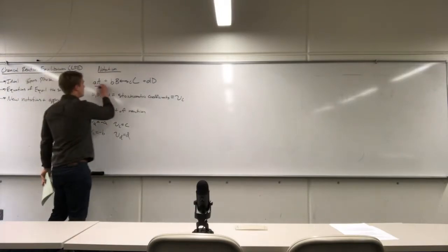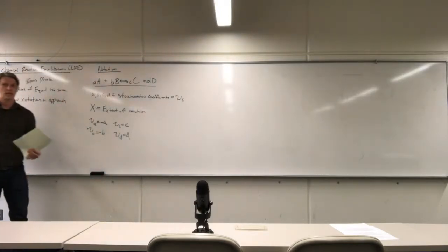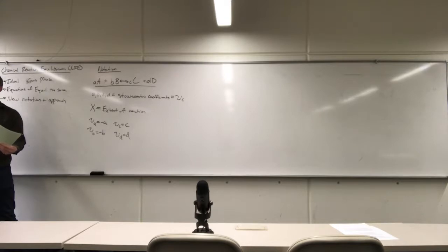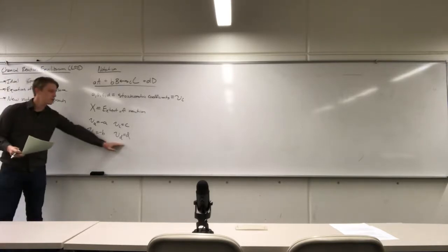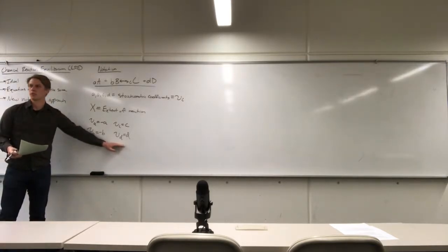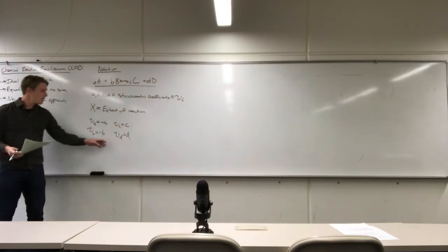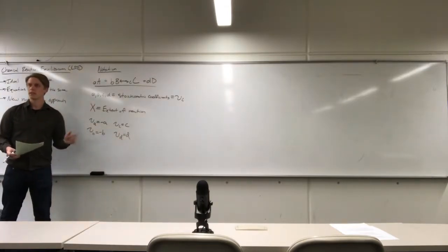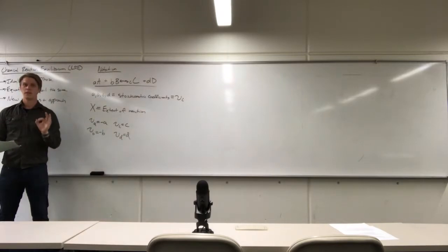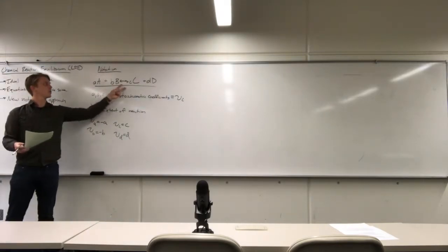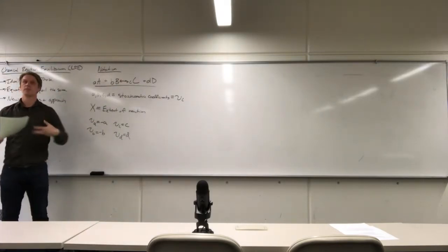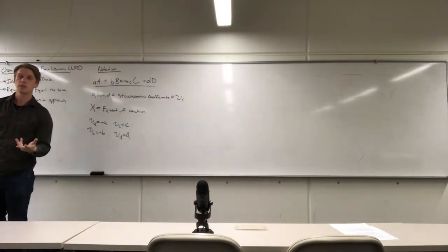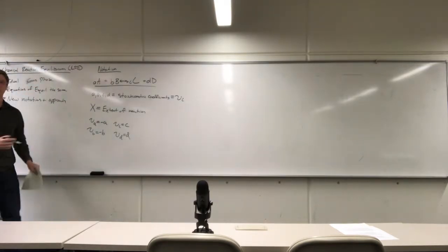When I write out a reaction, I don't actually know which direction it's going to go. That's going to be dependent on what the feed conditions, what the temperature conditions, what the pressure conditions are. But if we just adopt this system, then it's a lot easier for us to troubleshoot each other's work. But at the end of the day, if we screw this up and we flip this around, as long as you flip it around for all of your equations, you're A-okay. That effectively means you just switched the reactants and products. But since this is a reaction system, an equilibrium system, we don't care which side we're starting off on.